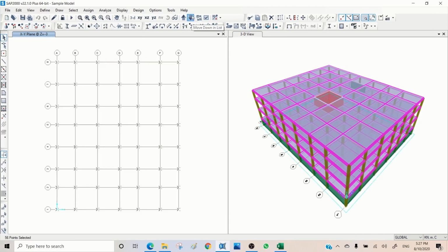So I will move back here and remove these grid lines. Those are for walls, and the rest of the grids and points are for columns. You see, I even extended the columns down to the basement. It really comes back to the structural system. It could be just the wall here and the columns end up here. If the wall is strong enough, there's no problem with that. It really comes back to the base level you have, which I will explain shortly after setting these supports.